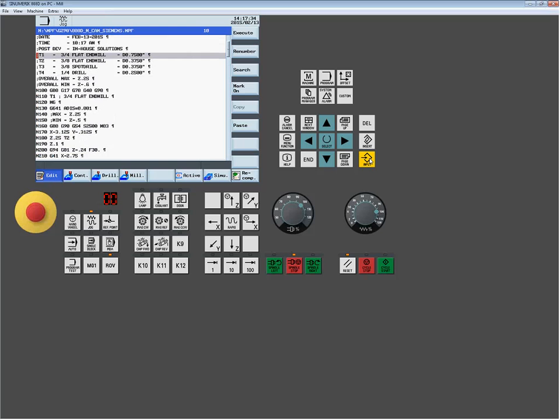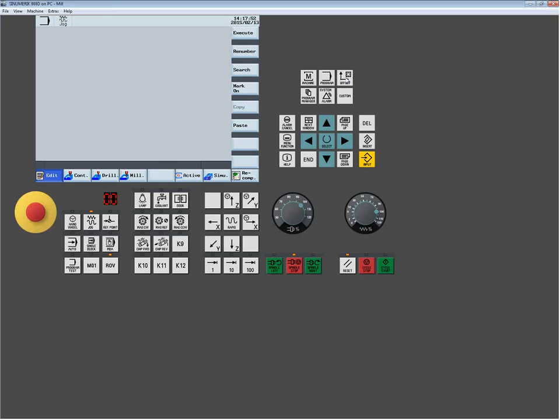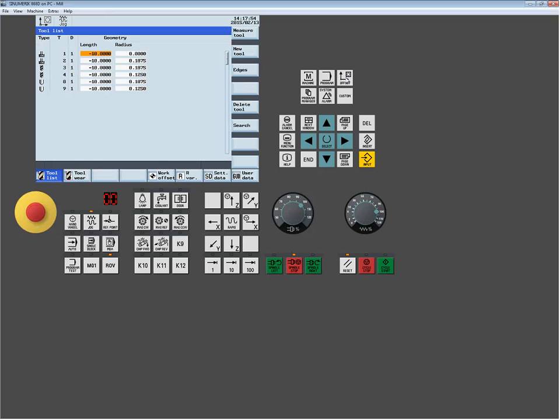And this is probably one of the first areas where the way the post is set up can dramatically affect how your part programs work. The post I'm using here, and the post and the protocol that this machine is running from, is really no different than an 828 and an 840. This is the same post that I actually use for 828 and 840 machines. However, this post was written for a machine that has a random style tool changer.